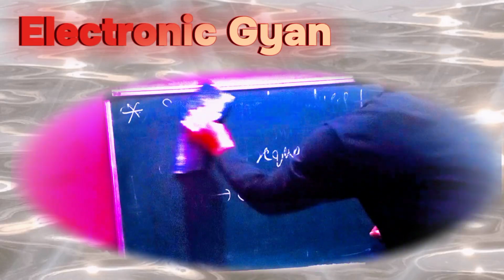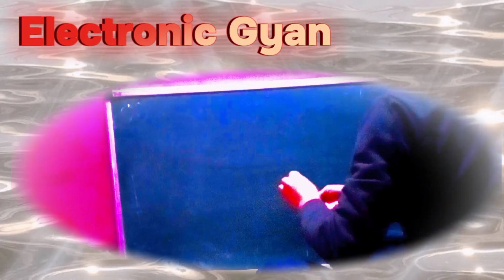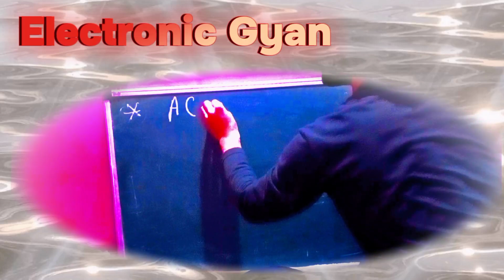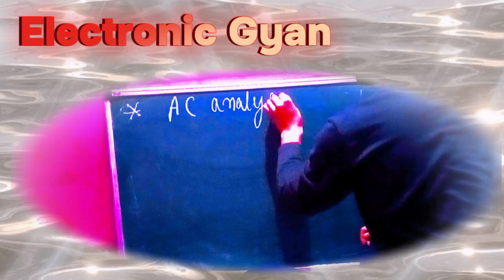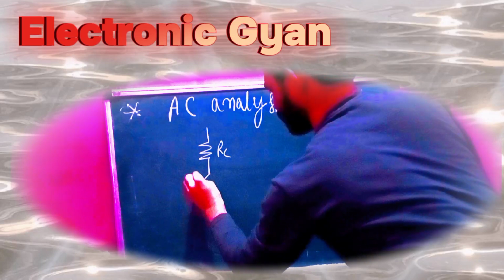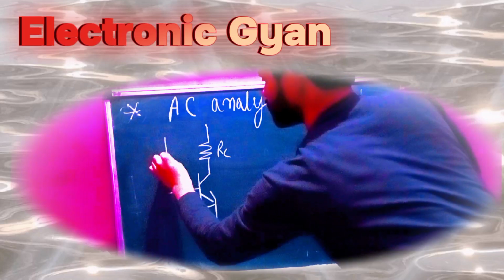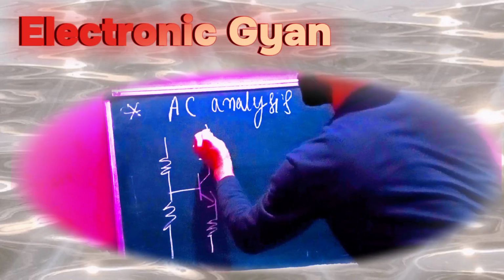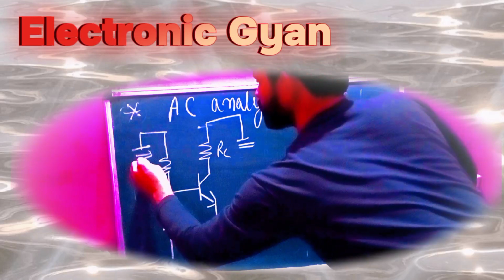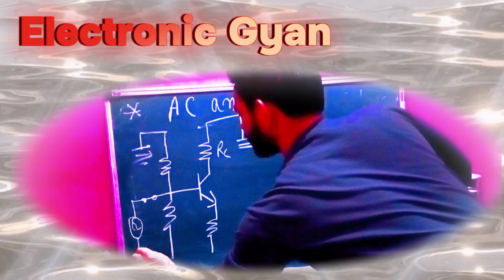Now see the small signal analysis, and which elements will get eliminated. In small signal AC analysis, this is my collector resistance, this is the emitter resistance, and this is my bias resistance. The supply voltage will get grounded, and this coupling capacitor will get short circuited, and the input signal will get connected.